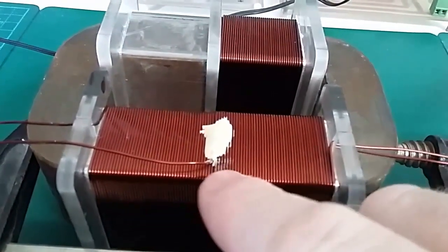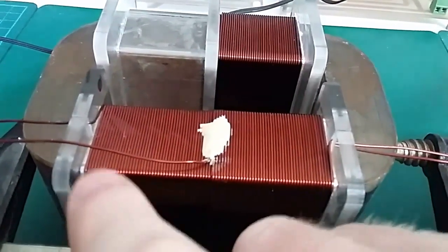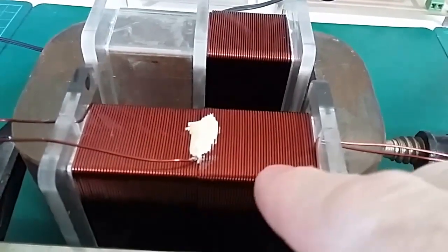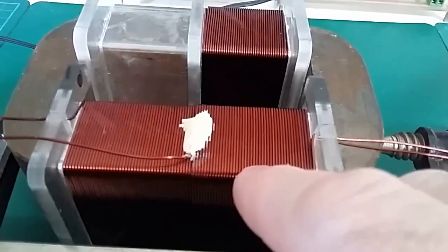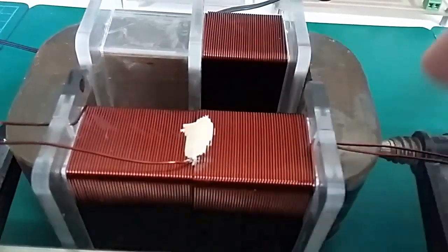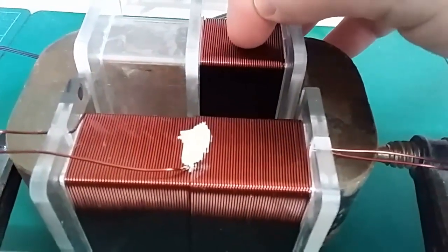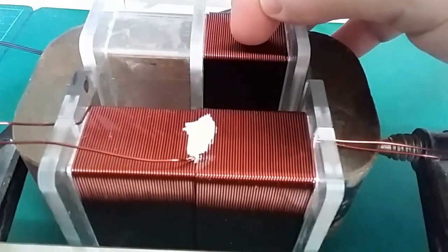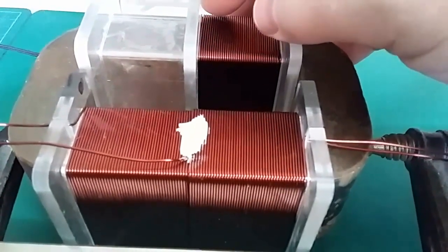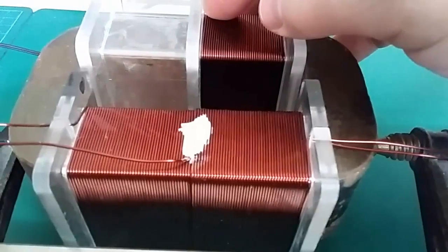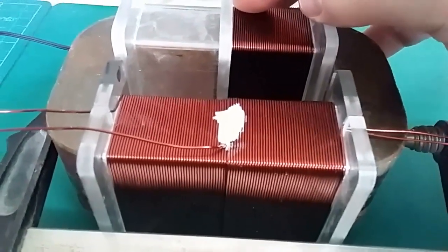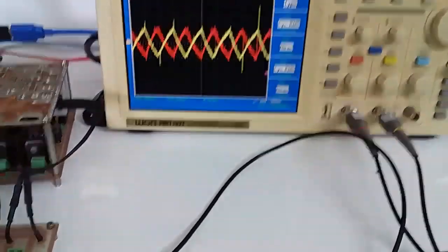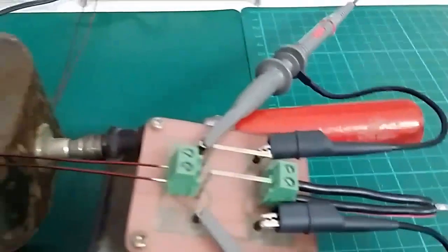What I'm showing here is that this coil is only one layer, 86 turns, and a half layer, which is 43 turns, inductively driving it from this coil over here. So please keep that in mind, because that is an important thing for what's coming up soon, and some of you already know why that is. Okay, so back to what we're talking about, the waveforms, the current through the coil.